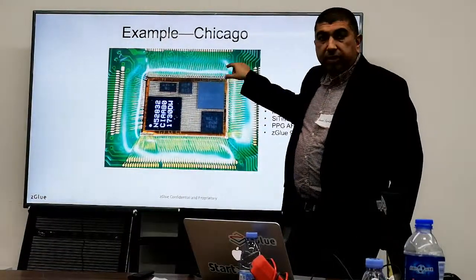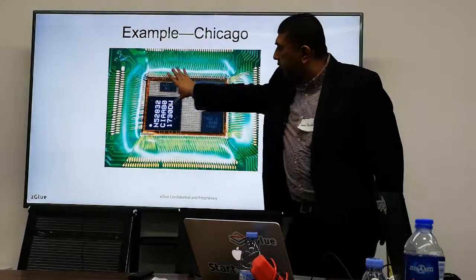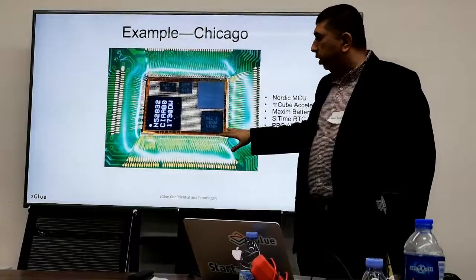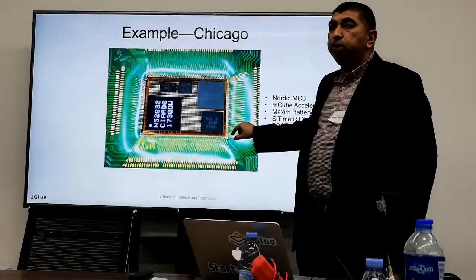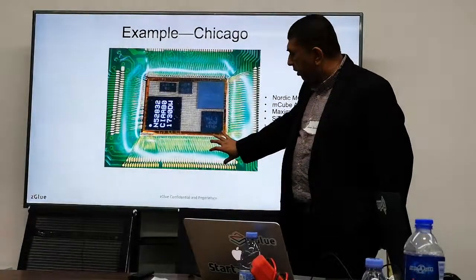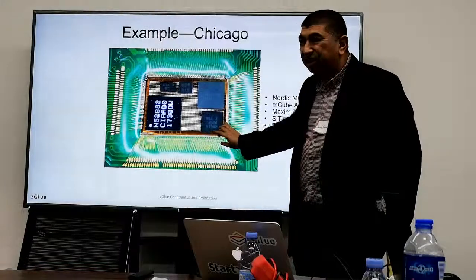But the interesting thing is, this particular one is a chip-on-board configuration. See, this combination is directly bonded onto a PCB. It can be bonded to a flex PCB also if you want a really compact thing, right? You can actually reduce this size further if needed.